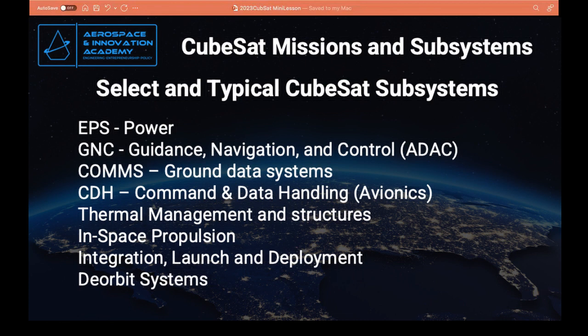The good thing about structures, if you're going to build your own satellite, is that there are a lot of commercial off-the-shelf parts. Even polylactic acid, which is a common filament in 3D printers. You have to make sure your components don't outgas a lot, and they do provide the properties you want. Another 3D printer filament, ABS, is sometimes used, or nylon. Composites are very popular because they're really strong and very light. Some of the most interesting stuff going on is thermoplastics, which are light as plastic, strong as steel.